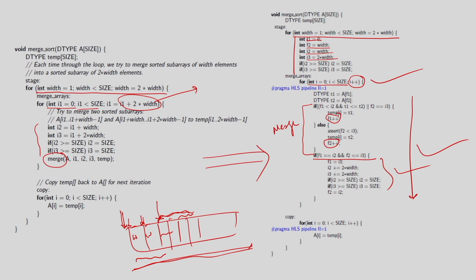So, you can understand the benefit that I am going to get. Earlier it was a 3 nested loop, I have now 2 nested loop, because I merged these last 2 loops into one loop, right. So, the operations of these two things into one. And the biggest thing that I can see here is this loop is now fixed size, right, and I can apply this pipeline at this level, not the innermost level.